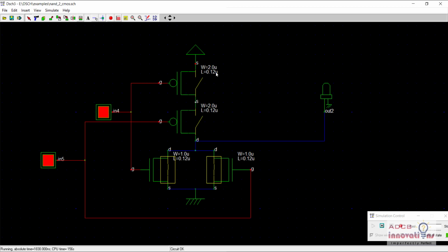Now I hope it will be clear why, when we supply 0 or when we supply 1, we are getting 1 or 0 at the output. So that is how our basic logic gates function. In other videos, we will see how to make an AND gate or OR gate using this structure. Alright, and what we are going to do is add the inverter in front of it, so that NOR becomes the complement and it gives the OR gate. So these are our universal gates, that is NAND, NOR and NOT gate.